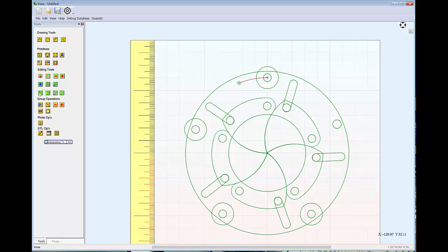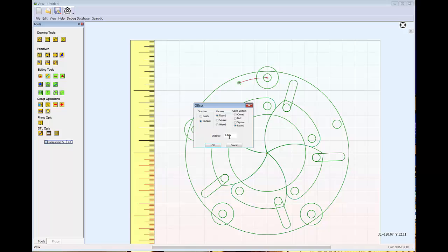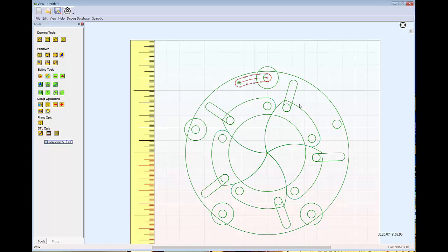And if we offset this arc by 3.125, we'll have a 1/4 inch slot for the ring to run on. Now select the center and delete it. We can select our little marker point and delete that. We can array copy this 5 times. We're not going to use this particular one. And now we can select those and add them to our ring.